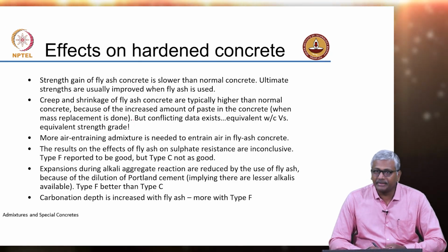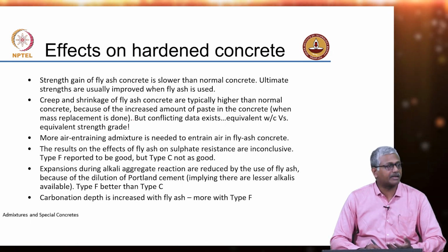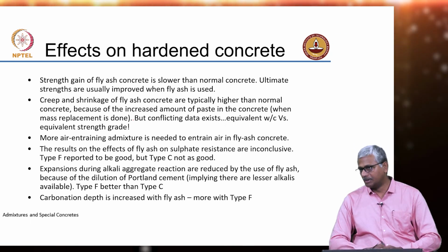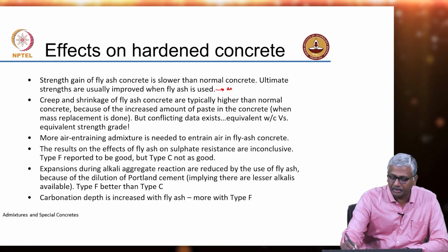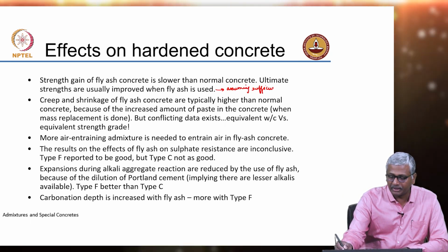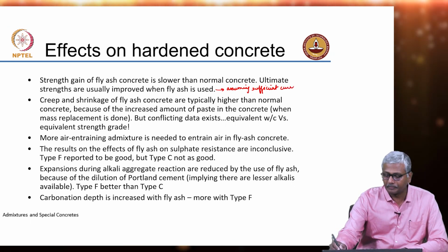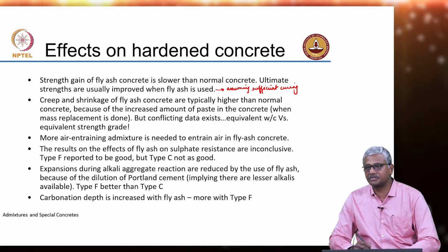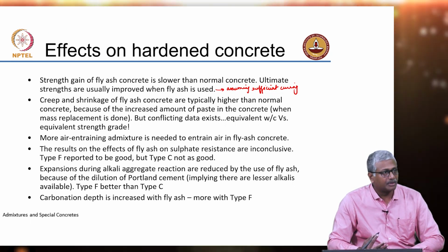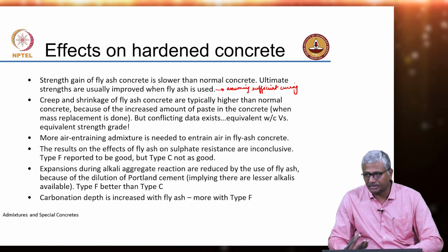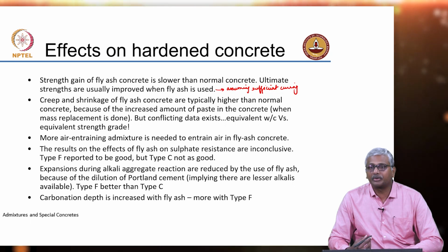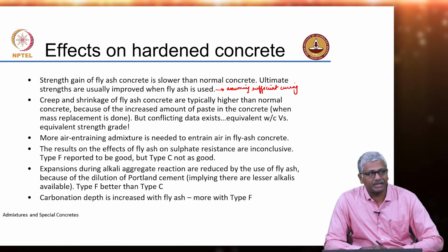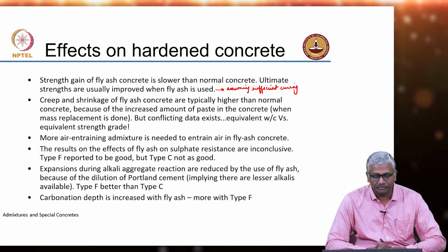Now, on hardened concrete, the effects are easy to comprehend with respect to mechanical characteristics. Obviously, the strength gain is slowed down, but assuming sufficient curing, the ultimate strengths are going to get improved. If you do not do sufficient curing, there is no reason for the concrete to continue gaining strength. The strength gain may stop because there is not enough water available, or your concrete water starts drying out, which indicates that your pozzolanic reaction will not get completed fully.